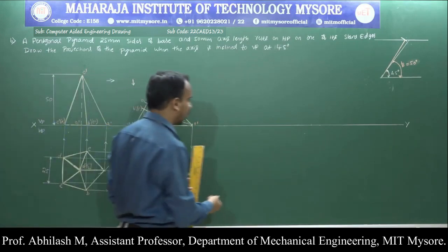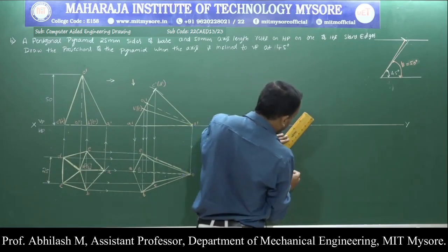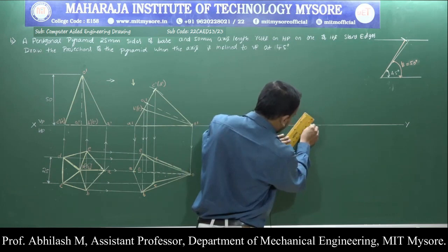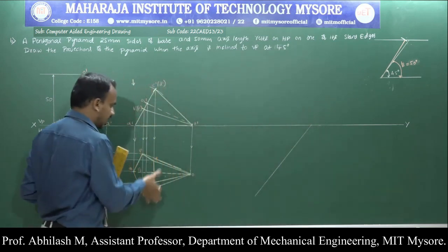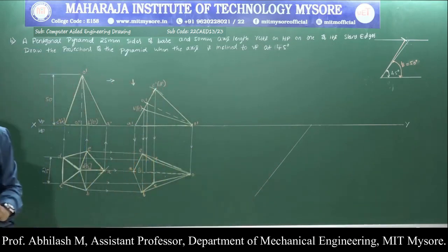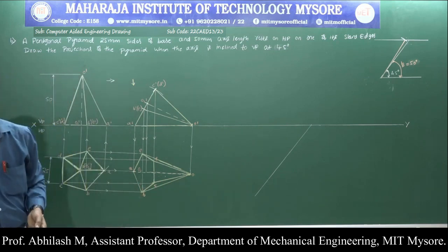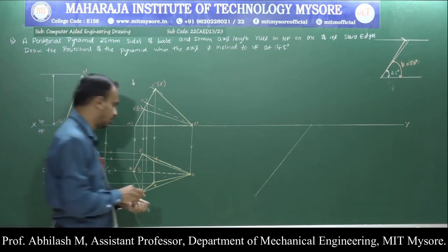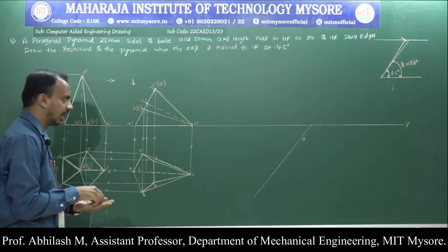So let us identify a point anywhere here, and draw a line which is inclined at an angle of 50 degree, so that we can transfer the entire second position onto that particular line. So how to do that? Again, we are supposed to follow the very known method, which is the arc method. So identify any O point first. This becomes our reference, in order to transfer completely.